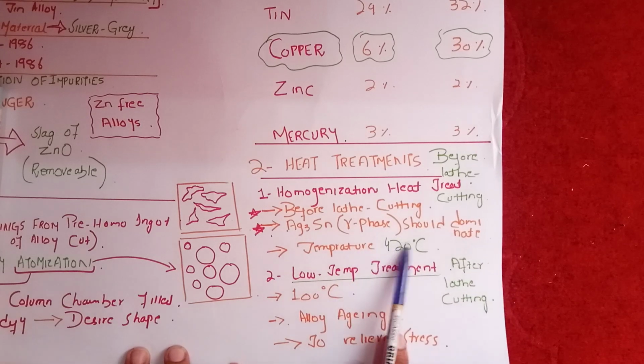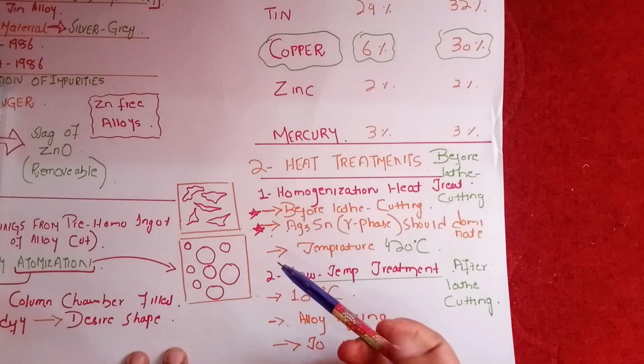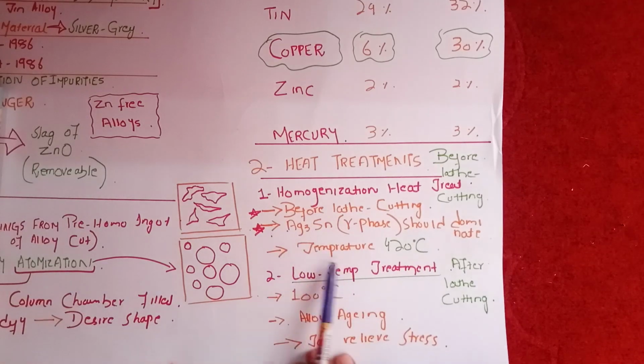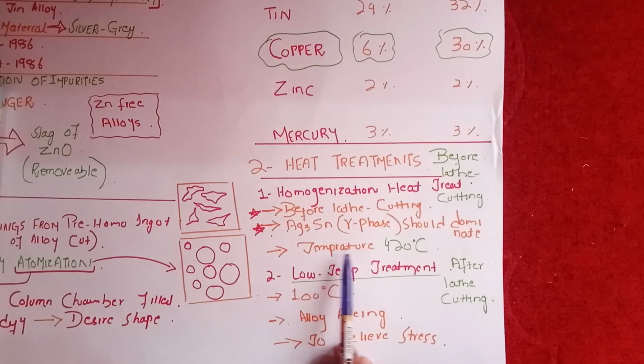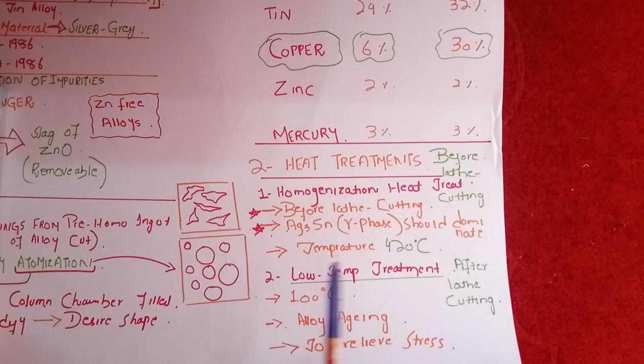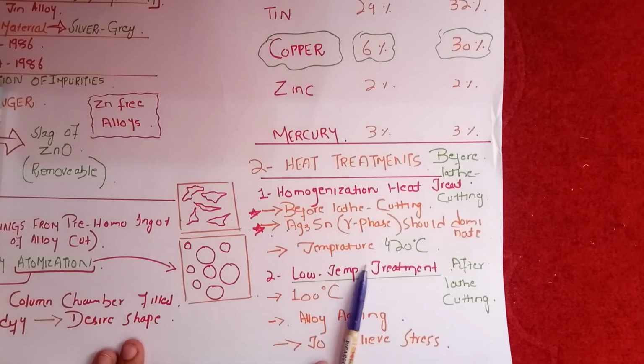During the formation of the ingot of alloy, there is a tendency for phase separation to occur and for a cored grain structure to be formed. The heat treatment involves a heating temperature of 420 degrees centigrade for several hours, and the resulting alloy contains relatively large grains of gamma phase material.